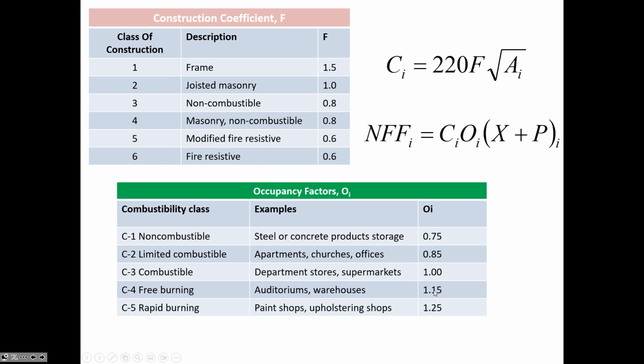So all these things are taken into account, and though you're unlikely to do a fire flow analysis for a building, I think it's important to be aware that you may design the size of a pipe that's going into a certain neighborhood, and just because you sized a pipe into one part of town based on the size of the land use area, it doesn't necessarily mean, even if the same number of buildings are going to be in a different part of town, that the fire demands could be the same, because there could be variation in the types of materials that are used for construction.